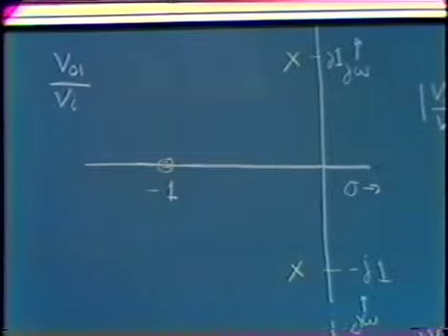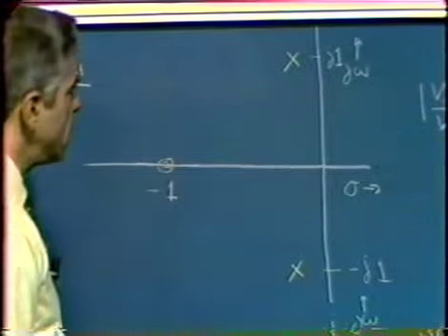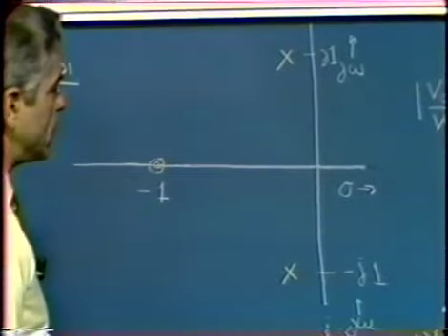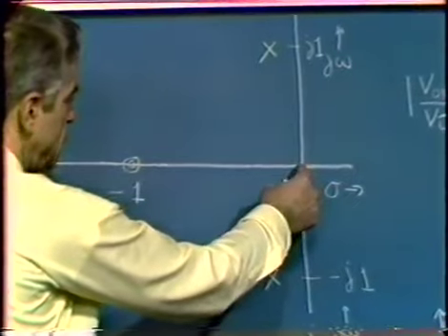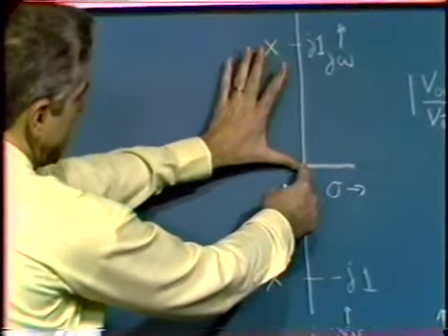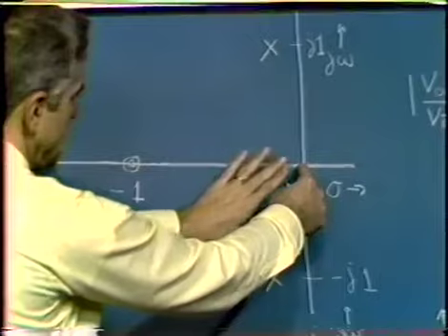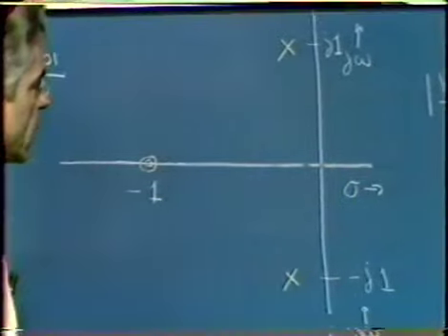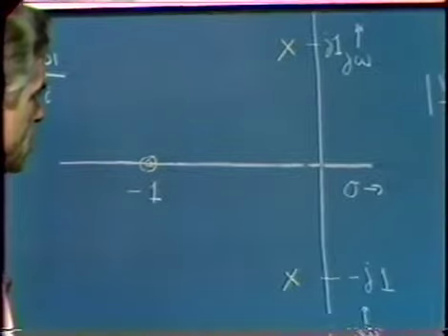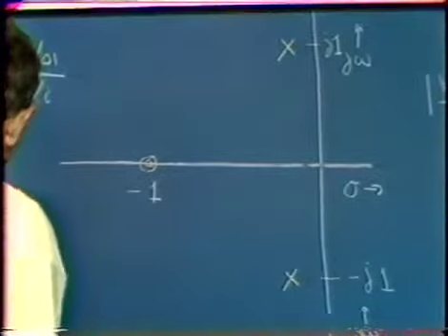And we can sort of rapidly sketch the frequency response of that system with the usual vector manipulations. We recognize that at DC, the length of a vector from a pole and a zero cancel. And since there are two poles and two zeros, we'd at least have a magnitude that we might normalize to 1 at DC.